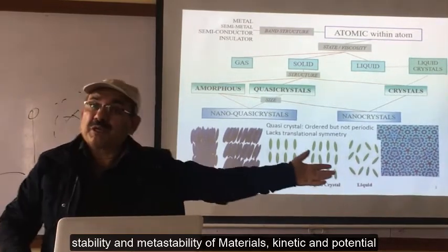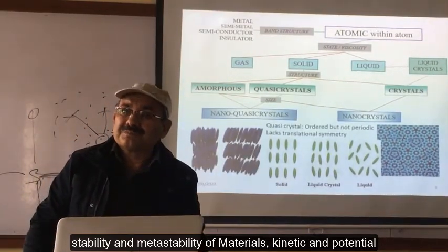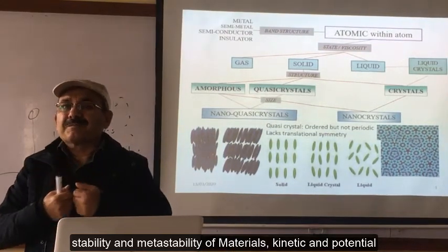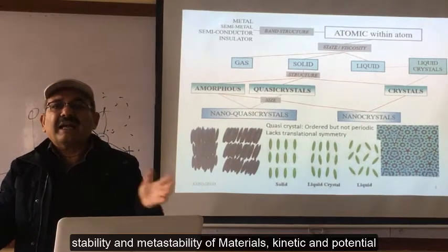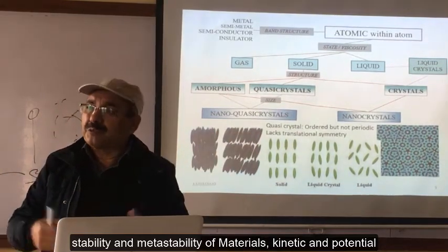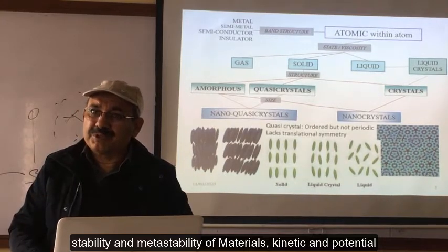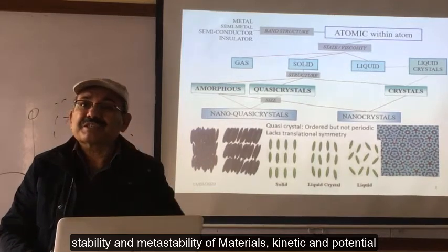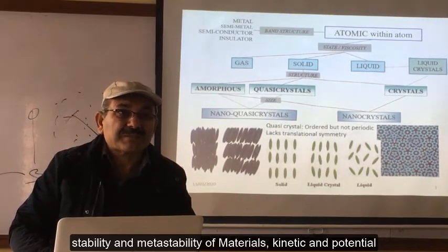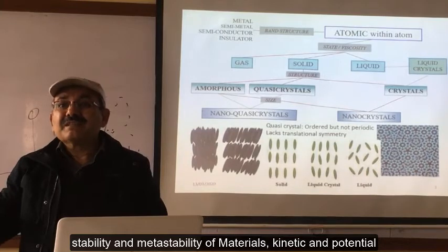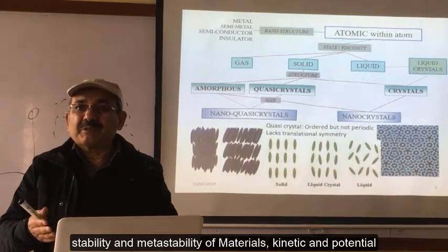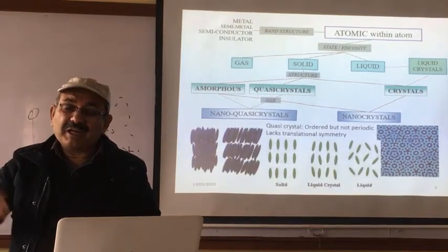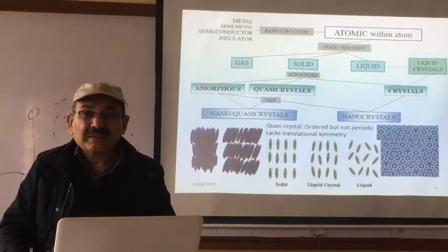You want to go out of this room, but I have locked the door. We are doing the same thing. We combine a material in a specific set of parameters and then don't allow them to come back. Whenever they find an opportunity, they will come back. And that introduces metastability in phases. Some phases are stable, some are metastable. Metastable means that when they find an opportunity, they will go to the stable state, after having that energy.